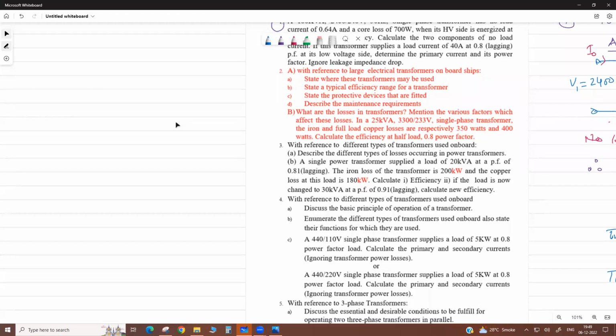But in dry type, the main cause of winding insulation failure is if there is a void, meaning a hole or crack, and when it absorbs some moisture from outside. Now moisture comes with dust deposit. When dust is deposited on the winding, in the dry type transformer we have to remove the dust periodically, weekly or even daily, depending on the deposit of dust.